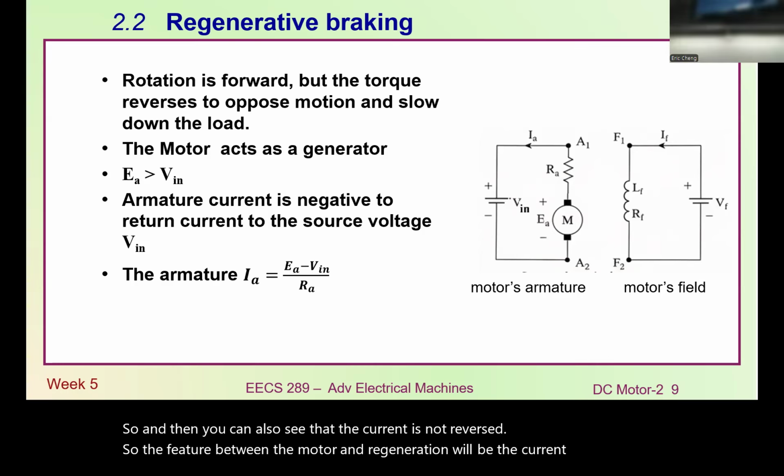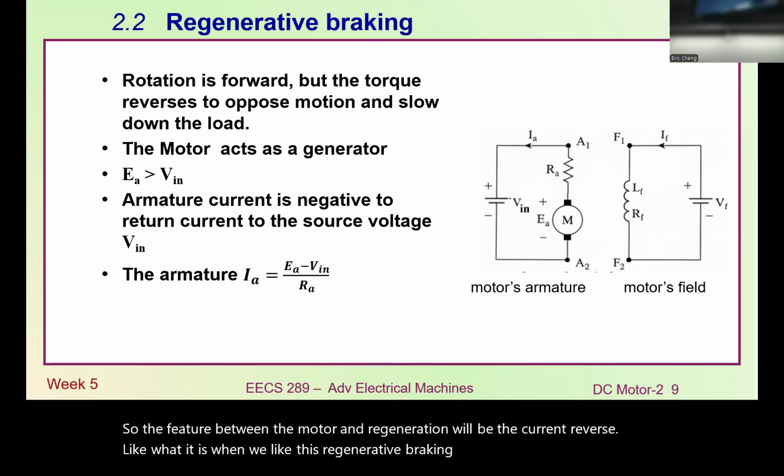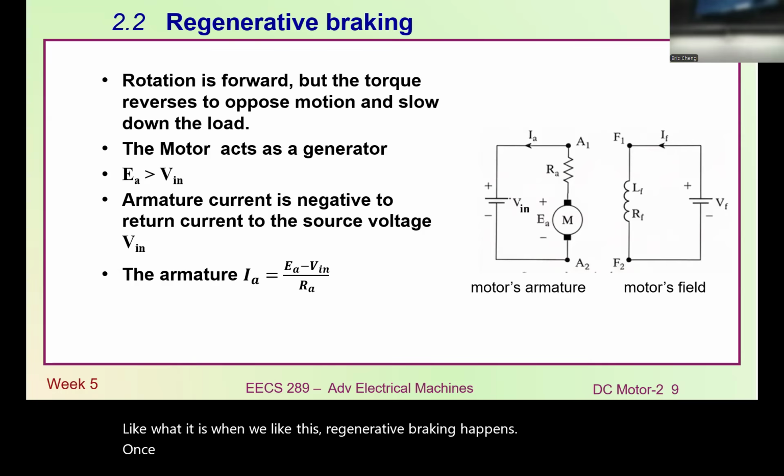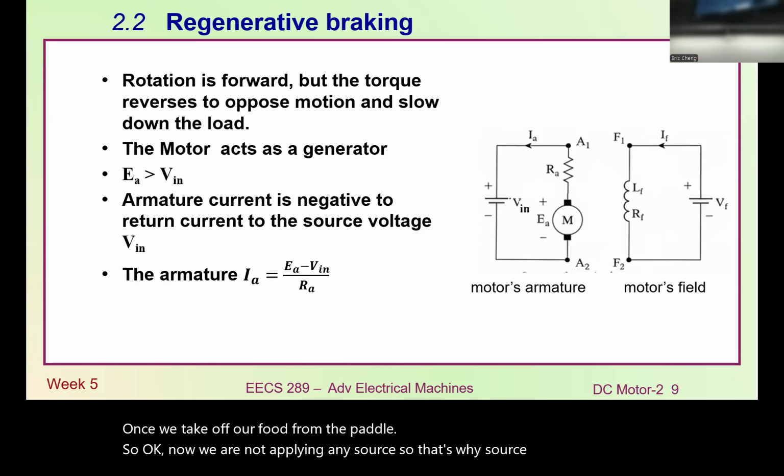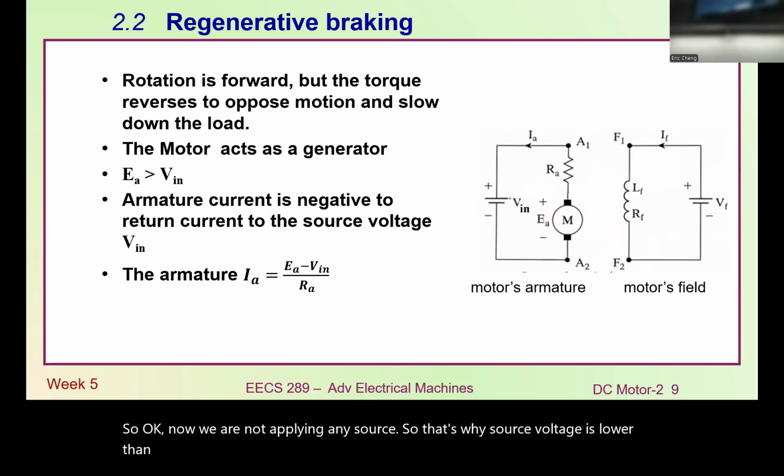Ali, can you explain a little bit more, like when this regenerative braking happens, once we take off our foot from the pedal, so okay, now we are not applying any source. So that's why source voltage is lower than the back EMF, right? Exactly. That is the way to control the motor. You mentioned a really good point, how we control the motor.